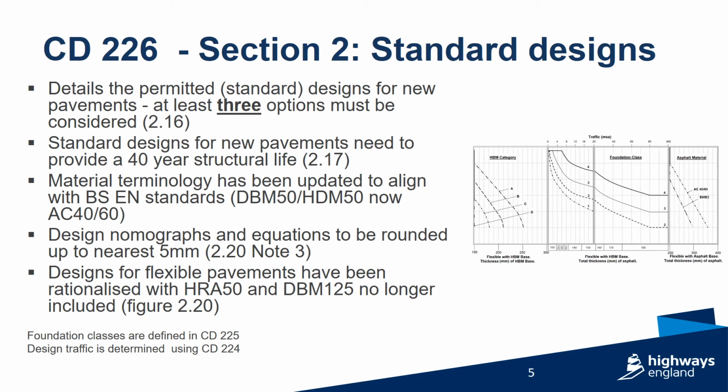Section 2 covers the permitted standard designs for new pavements. Clause 2.16 requires a minimum of 3 standard design options to be considered. Permitted standard design options are flexible pavements with a lower base layer containing asphalt. These are designated as flexible with an asphalt base.